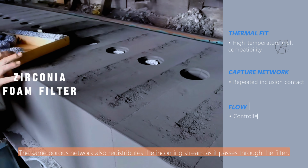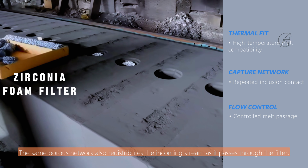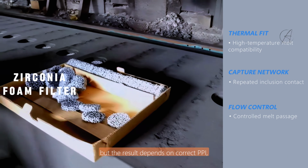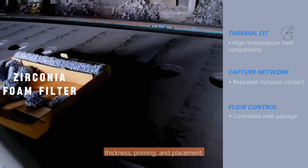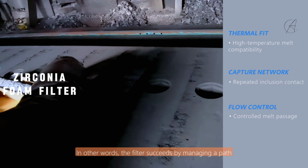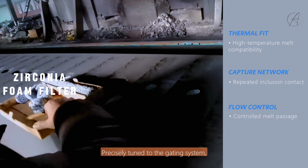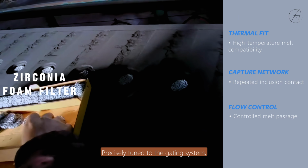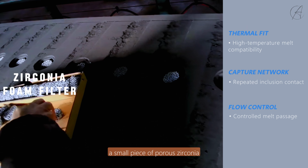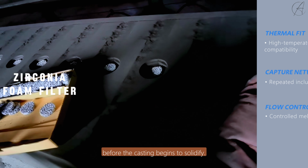The same porous network also redistributes the incoming stream as it passes through the filter, but the result depends on correct PPI, thickness, priming, and placement. In other words, the filter succeeds by managing a path, not by acting as a passive block. Precisely tuned to the gating system, a small piece of porous zirconia can influence what reaches the mold long before the casting begins to solidify.